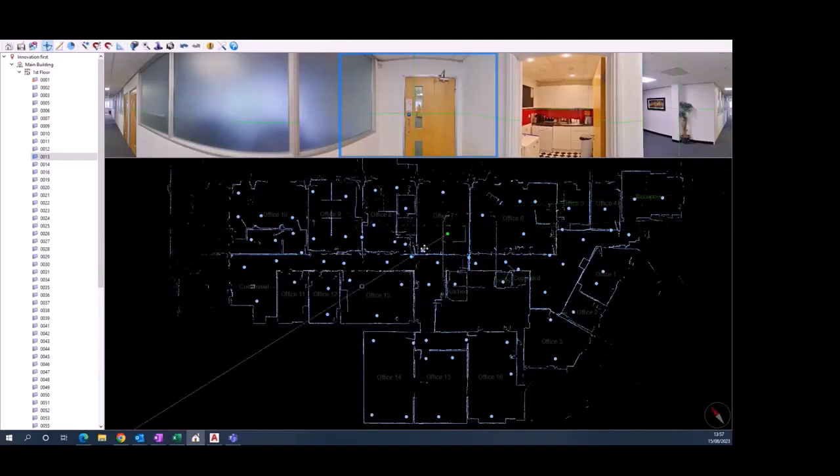One thing I found when I was doing this scan is if you put the camera and take a scan in the opposite direction, it loses its orientation. So we'd end up with something like this. So that's clearly the wrong way around. So you can use this tool to make corrections like that, put things back where they should be. Again, if I Control Z back to the beginning, it will put it back where it came from. So that's really useful, particularly if you're doing a new scan of a room that's changed, and then you can overlay it back onto this overlay.